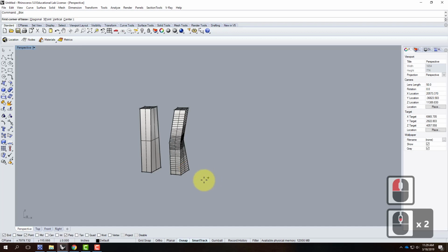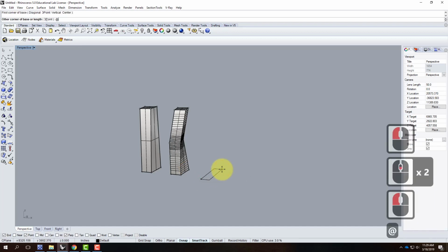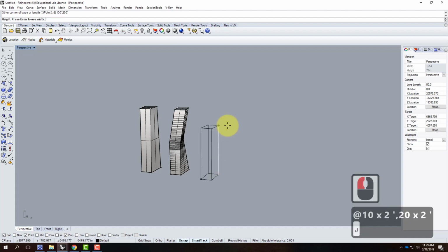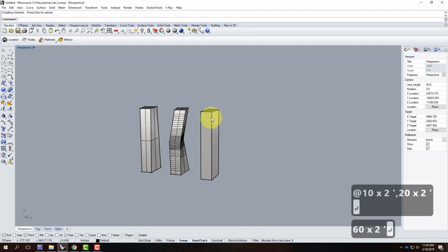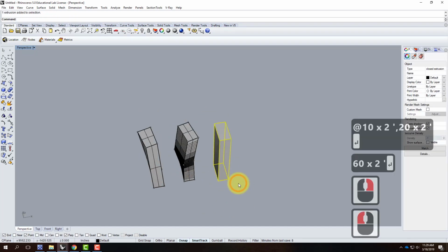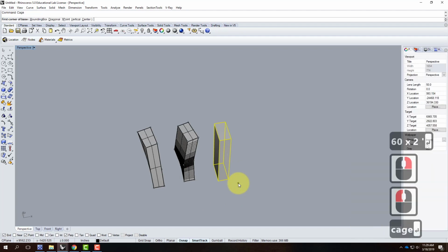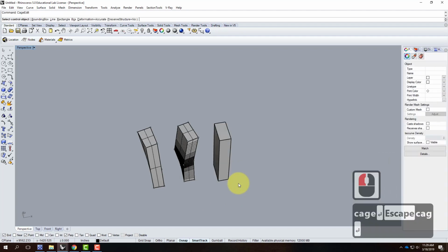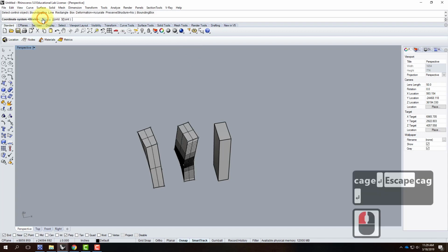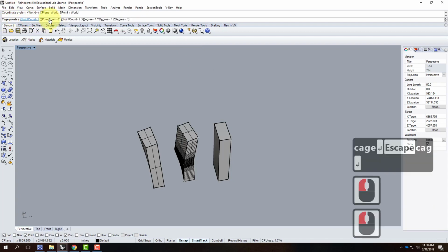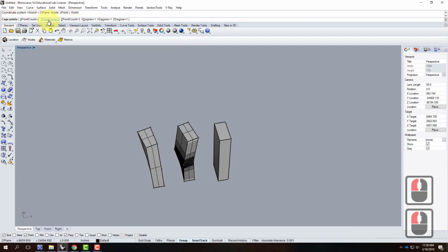So if I did the same setup with the same control points, so this is again at 100 feet, 200 feet by 600 feet. If I did the same cage edit here, cage edit, bounding box, world, same x is 2, y is 2, z is 3, but I changed the degree of z to be 2 instead of 1.